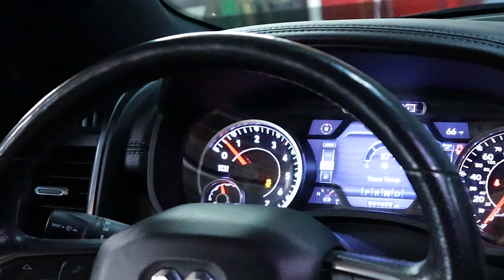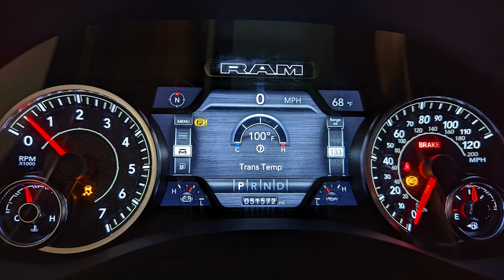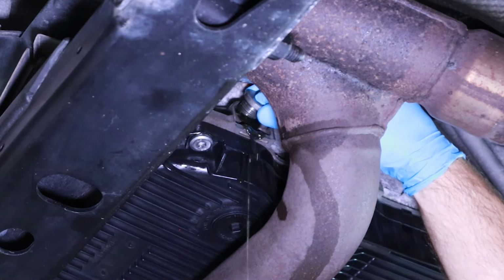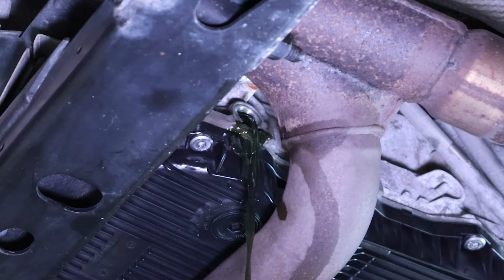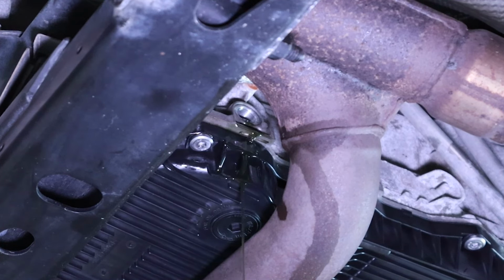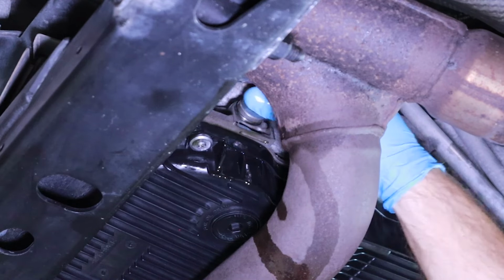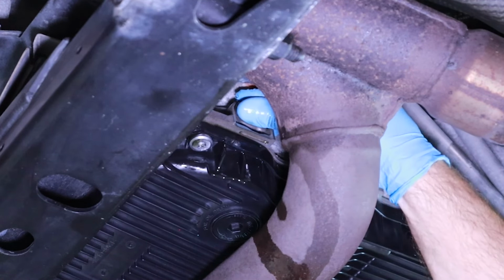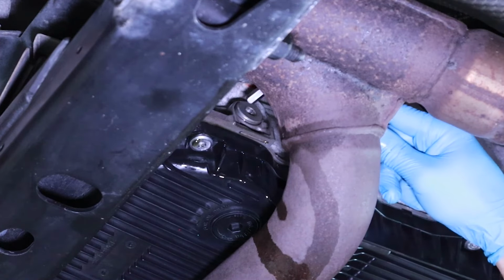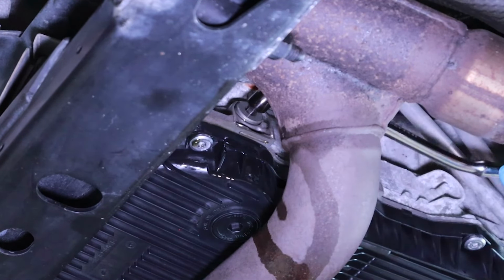With the engine idling, begin monitoring the transmission temperature. When the temperature is in the 86 to 100 degree temperature range, remove the fill plug and allow the excess fluid to drain. The transmission fluid level is correct when a steady stream of fluid flowing from the fill port transitions to a light trickling stream between 86 and 122 degrees. Once this is observed, the fluid level is correct, and you can now reinstall the fill plug, tightening it in a clockwise direction using an 8mm hex bit socket and torque wrench to the recommended 25 foot-pound torque specification.